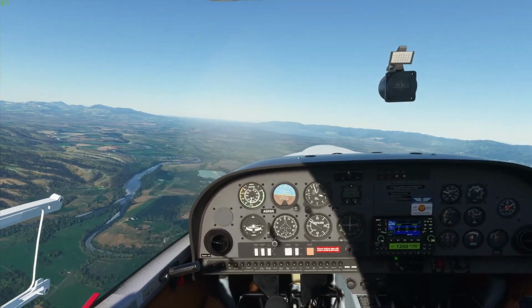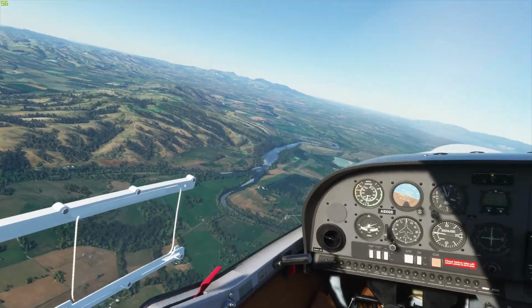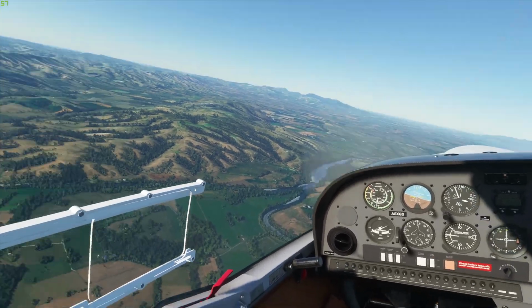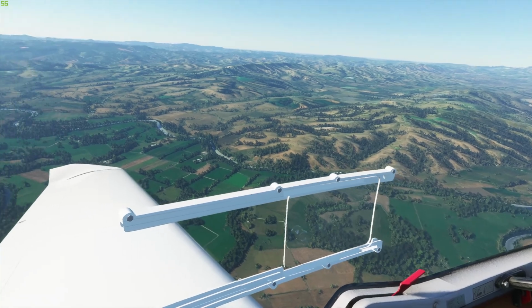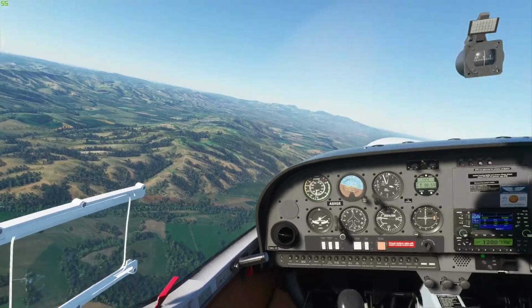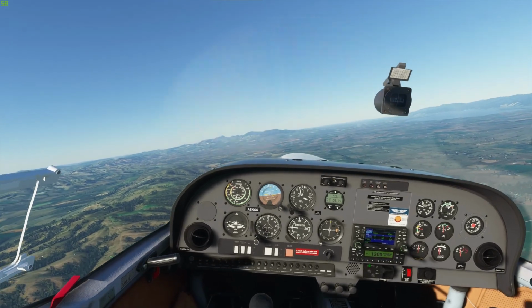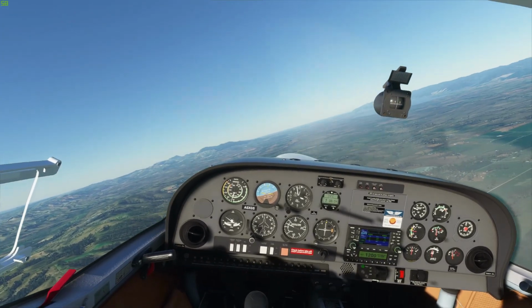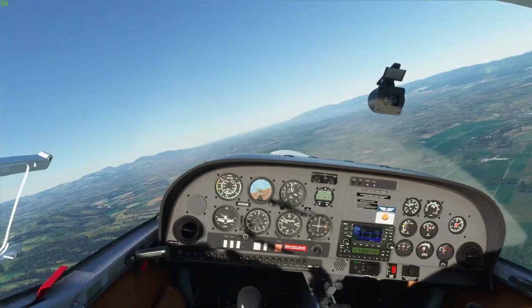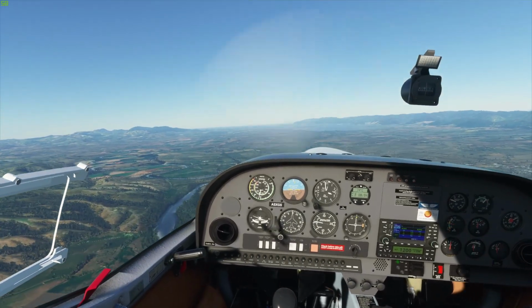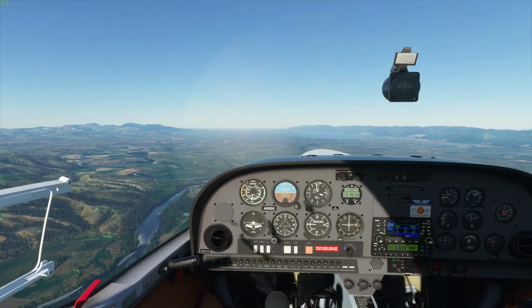And lookout, so we'll just do a quick S-turn here to make sure we've cleared the nose in case there was traffic under the nose. And I'll make a radio call. Nice in traffic, Delta Mike Oscar is operating 5 miles south of the field at 3,000 feet. Okay, no traffic, so we'll roll back out on heading 210. And I will close the throttle.